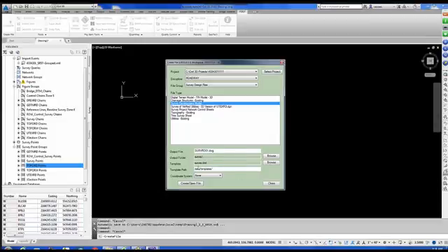Now, so here's our file name. Here's where it's going. It's going in the survey folder. That's why it's important you use the FDOT Create Project tool to create your project so the directory structure is correct. All right, it's using a template called the survey.dwt. Okay, that's supplied in the State Kit. And then the template path, it's finding this off of the C drive where the FDOT State Kit is stored when it was installed. And we're going to go ahead and set the coordinate system at FL North. Now, if you forget to set the coordinate system, at the command prompt, you can type in set FL North, and it will automatically set the coordinate system up for you to the right coordinate system.